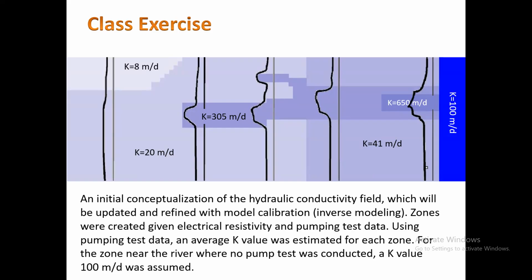My system also has boundaries. For example, in the problems that I gave you, I told you this boundary here is a groundwater flow divide. This means that this is a no flow boundary. You can think of it as a watershed, where water flows down.